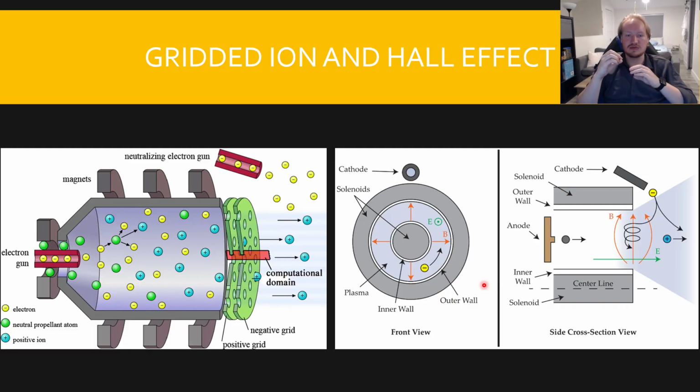When we then push our neutral propellant ions into that high energy ring, they're going to ionize, and those positive particles are going to be carried in the inverse direction along this electric field and accelerated out very, very quickly. Additionally, after these positive ions have left the system, electrons from the cathode are also attracted to those positive ions and cause them to neutralize.